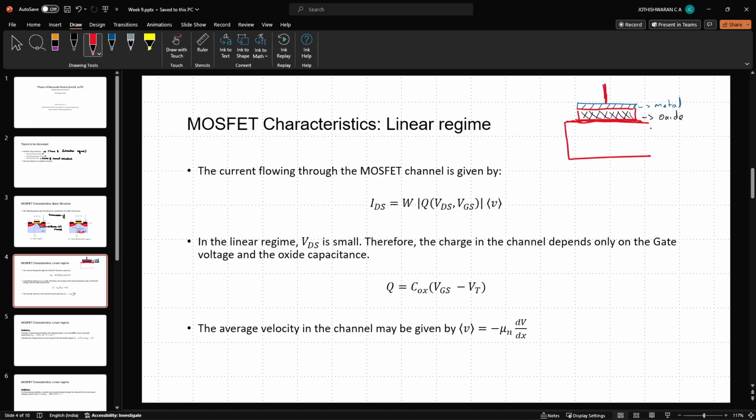Essentially it is going to be like VGS. So I have a Vs here also. Typically, this and the source have the same voltage. Right now, there are no source and drain contacts. So this is the substrate. It can be treated as a capacitance, where I have a voltage applied across these two, and the oxide in the middle plays the role of the dielectric. So this is a parallel plate capacitor.